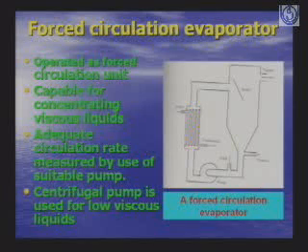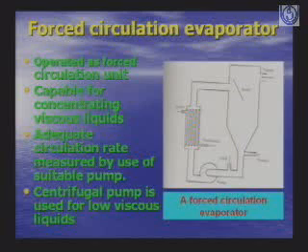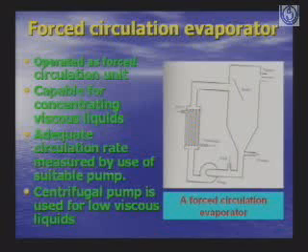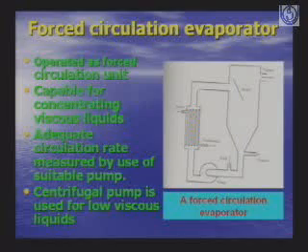There the steam is passed to the product, and the product is at the lower side, where the pump forces the product upstairs, then boils it. With the help of steam the product is boiled and becomes concentrated, and then the vapor goes upwards and outside, and the concentrated product is received from the lower side.